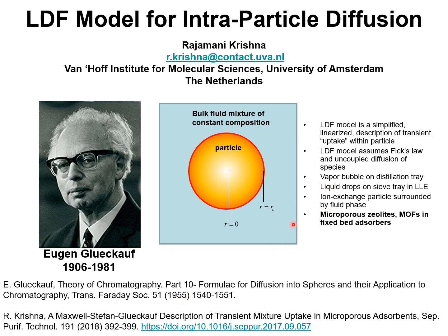The LDF model applies not only to spherical particles of solids, but it can be applied to vapor bubbles on distillation trays, liquid drops on a sieve tray in liquid-liquid extraction processes, and ion exchange particles.